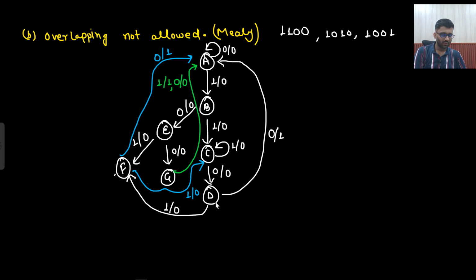Okay. So I know these are complex, but if they ask you to analyze this, will you be able to analyze this? Yes. You can tell that there are 3 times 1, 1, 2 and 3. 3 times 1, that means 3 sequence has been detected. How will you read it? You just need to go in the next state, 1 1, then 0 and then 0. So 1 1 0 0. And if they ask you whether it is Mealy or Moore, you can directly see it is Mealy only.